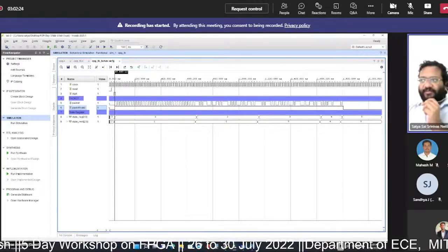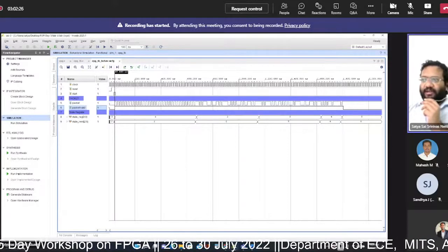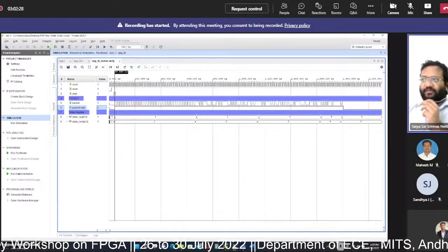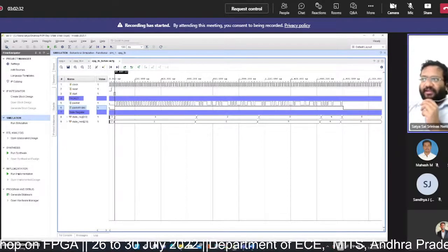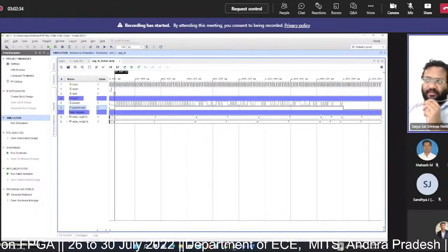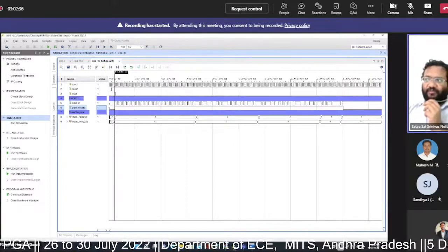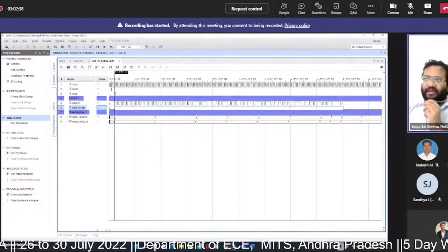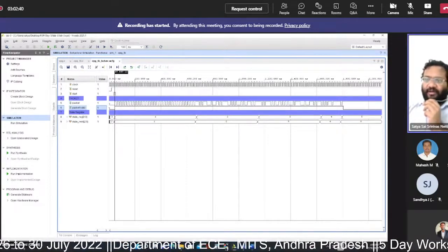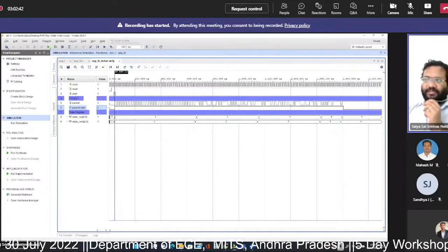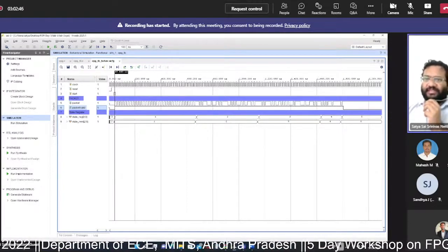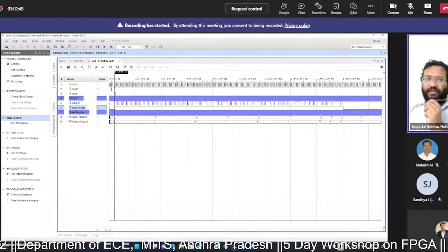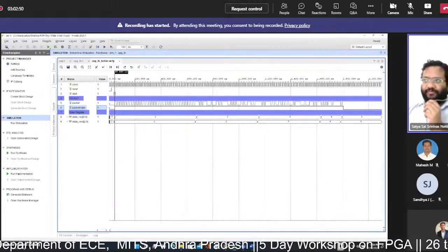Once the FIFO generator had the required number of data samples, I interfaced it with the Ethernet packet generator. Then I read the data samples from the FIFO, and those samples I serially fed out on the packet output.